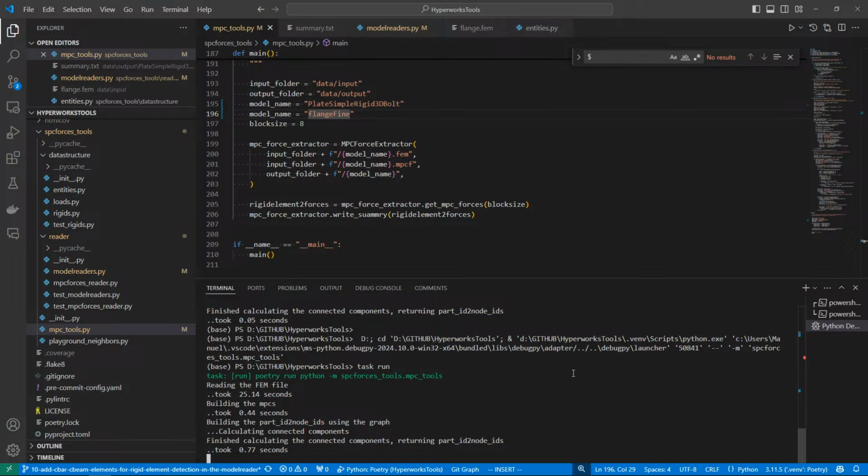What solver do I use? In my everyday professional life, it's mostly ANSYS. Depends on what problem we have. If it's a small project, it's just ANSYS Workbench. If it's larger projects, we have HyperMesh in combination with ANSYS Classic, but that's also a little bit legacy. And then we can also use OptiStruct. Those are the solvers we pretty much use every day. We don't have Abaqus. We have MSC Nastran also, but we're not really using Nastran.